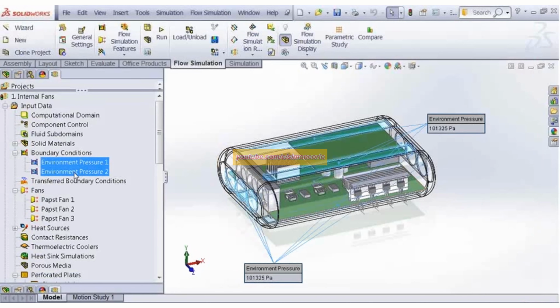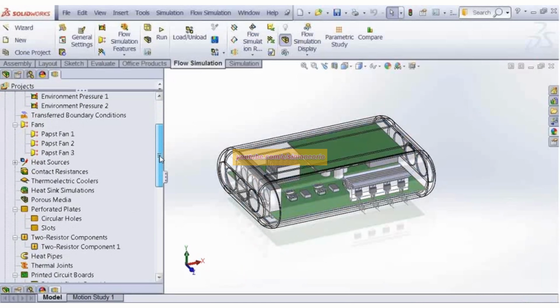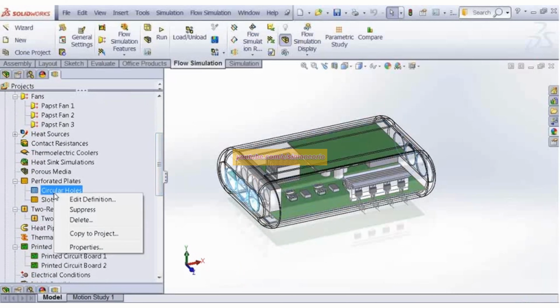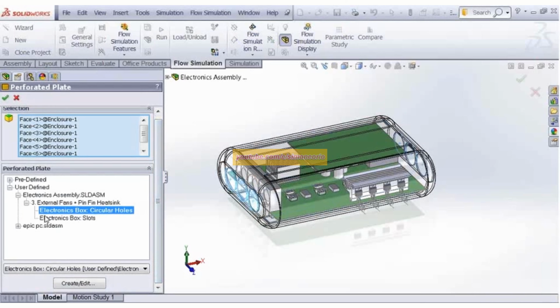And then how is the air getting in and out? So I mentioned this is an internal flow simulation, meaning that our volume is basically capped off. And so we're defining our relationship with the rest of the environment via a few idealized boundary conditions representing internal environmental pressure. And then as the air is coming through these boundary conditions, we're representing a pressure restriction of perforated plates, once again using an idealized model from our engineering database for flow.